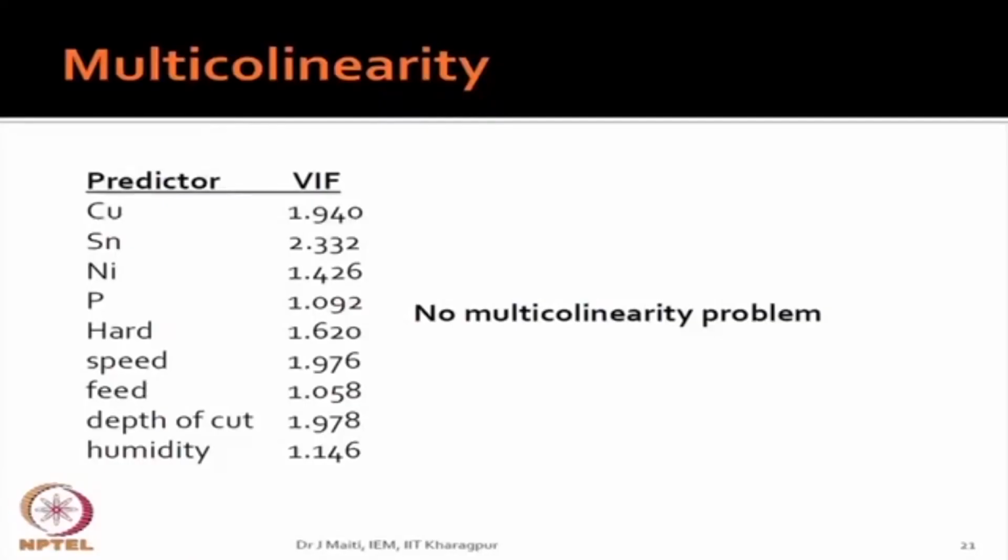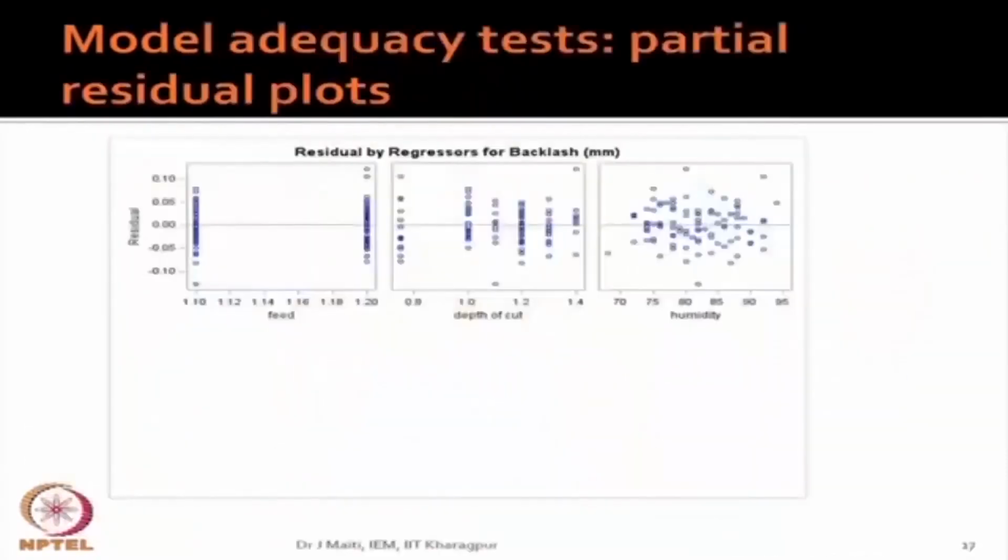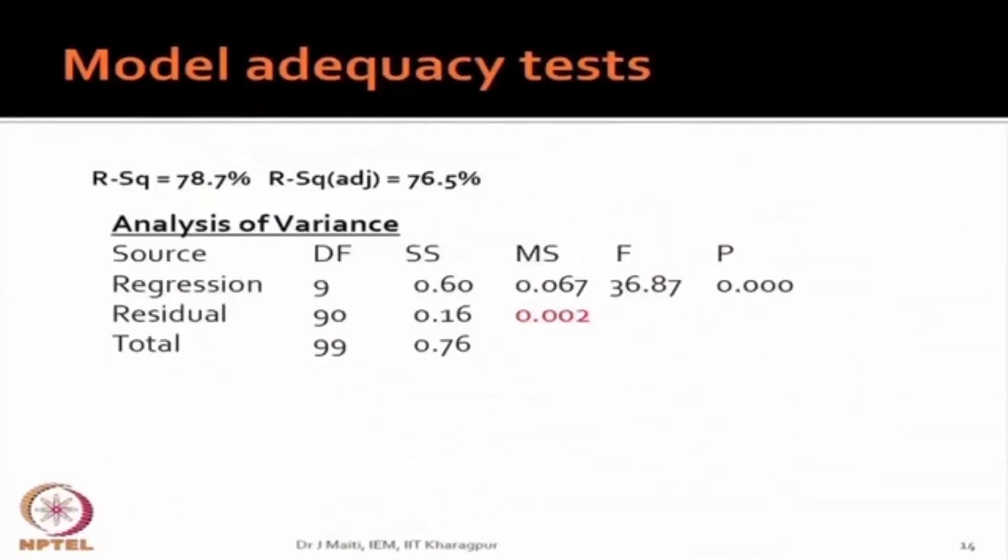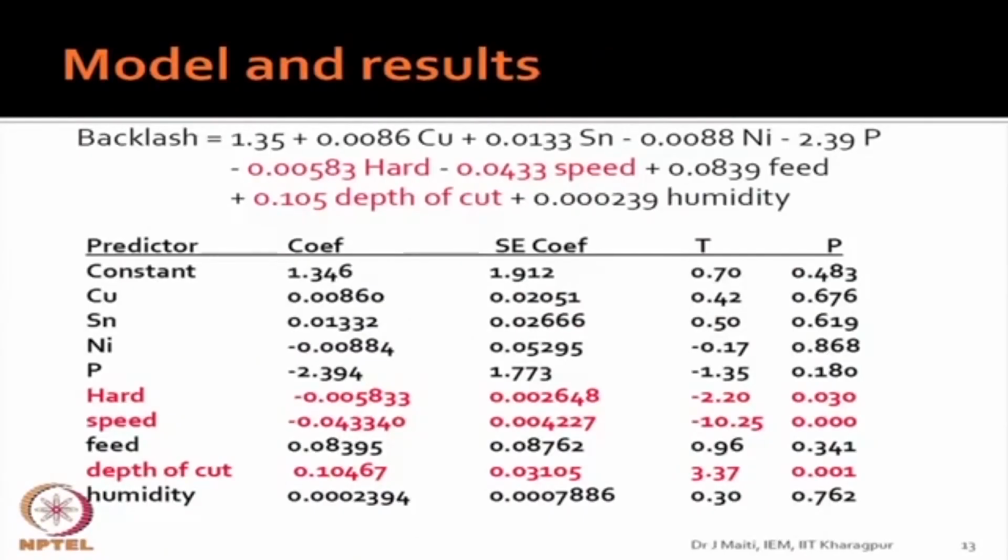So what is your conclusion about the process? The process variables are able to explain, including the input material, and we have found that 2 variables emerge as significant, among 3 variables: speed and depth of cut. These are process variables where you have control.